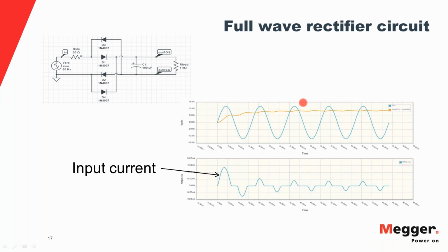At a certain point, it seems that the voltage across the capacitor is stable, but if you look closely, you'll see that it's not a straight line. You'll see that it charges up by a little bit and discharges until the next cycle, and the process is repeated every cycle. So you get this kind of a waveform from a rectifier circuit.